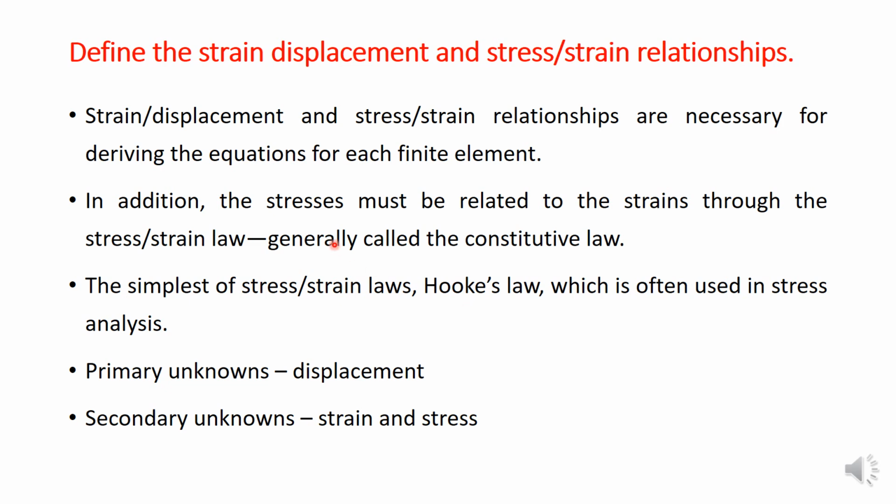Again, for two-dimensional and three-dimensional problems, the strain displacement relations may vary, because in two-dimensional problems there will be strain both in x and y direction. You're familiar with the equations: epsilon x equal to du by dx, epsilon y equal to dv by dy, and gamma xy equal to du by dy plus dv by dx. So these are the equations in the case of two-dimensional problems.